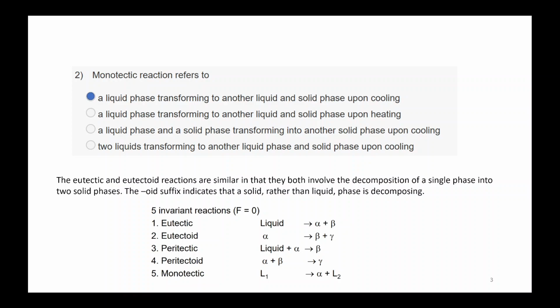It has a high number of dislocations and twins, so that gives it different properties compared to your pearlitic structure. It won't be like metallic glass here, because metallic glass requires much higher cooling rates compared to martensite. Okay.